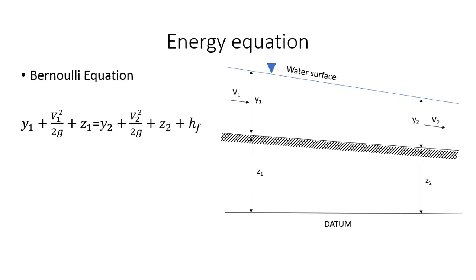Right? As you're all aware, this friction losses, we have dealt with this for a significant portion of the semester. hf is simply f times L by D times V squared by 2g. If you remember, this equation was developed for circular pipes, right? So if you want to use it for non-circular conduits, even in the case of pipe flow, we had developed this concept of DH.